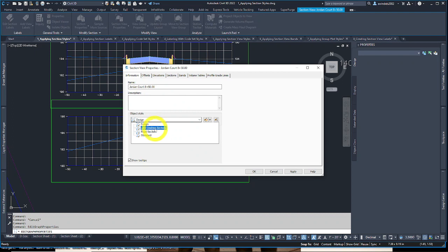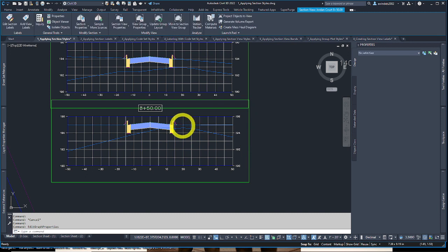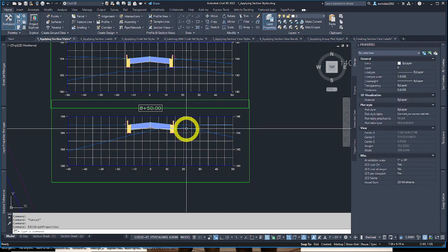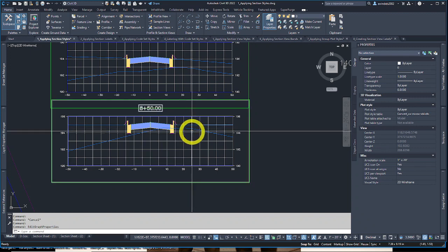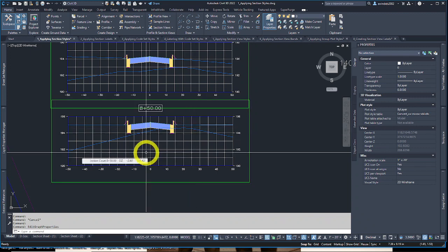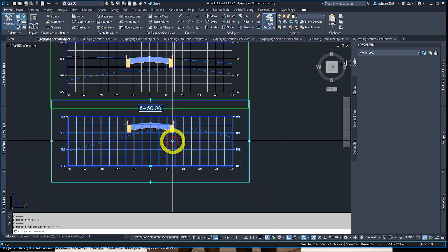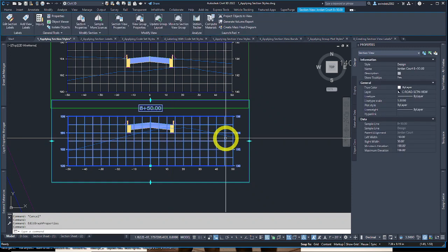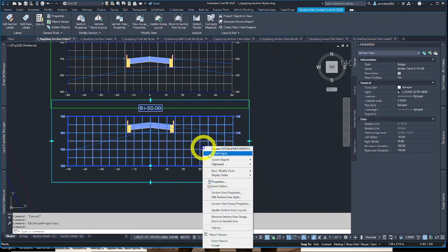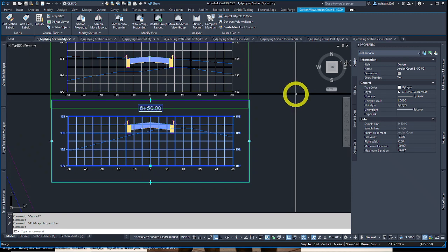And we're going to change this section view to, sorry, this is the section view, so quick learning lesson. I'm in the section view styles. I want to go to the section styles. So in order to get that correct, let's restart this. If I click the section view, I have options in my contextual ribbons, and I have my right click options as usual with Civil 3D objects.